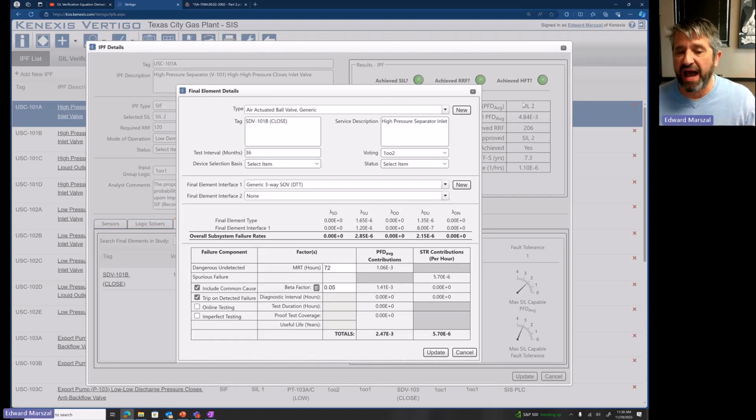So that's how we're basically assuming if your component is in the failed state, it will either be a vote to trip or not a vote to trip based on what this flag says, vote to trip or not vote to trip. So we're not doing any more advanced, okay, switch it to 2 out of 2 here, and if you get 2 degradations, switch it to 1 out of 1.